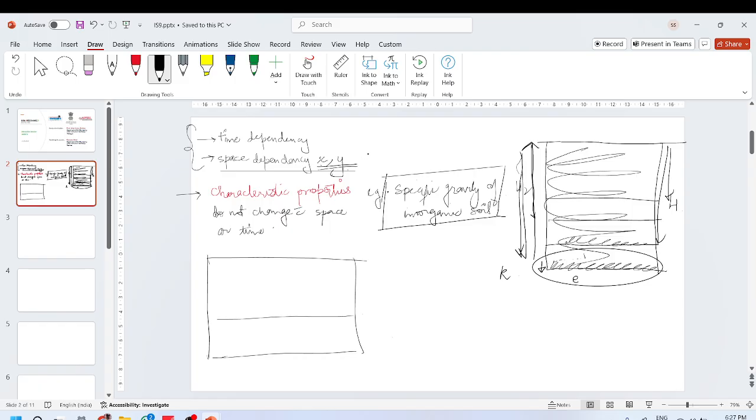And partial differential equations is what basically the seepage net is, where we write del square h by del x square plus del square h by del y square equals zero, with the streamlines and the equipotential lines like this. Now, time dependency comes into play when we talk about consolidation.